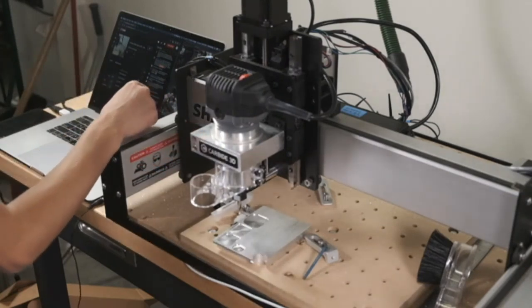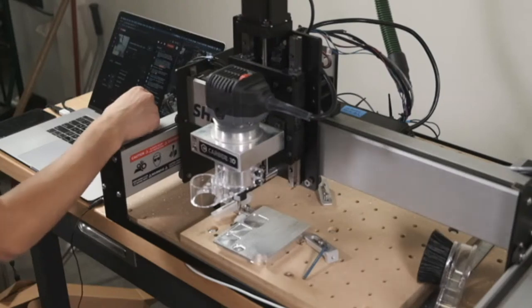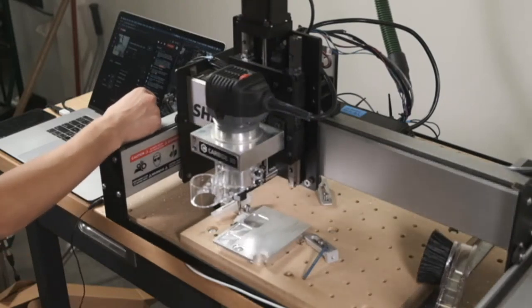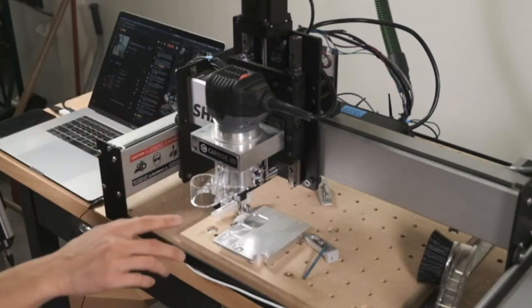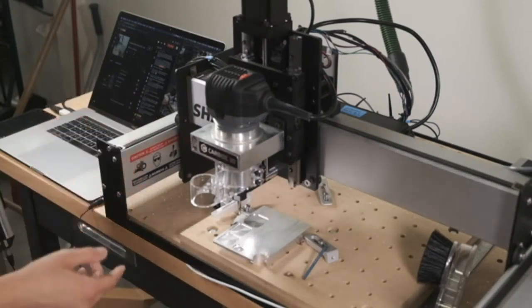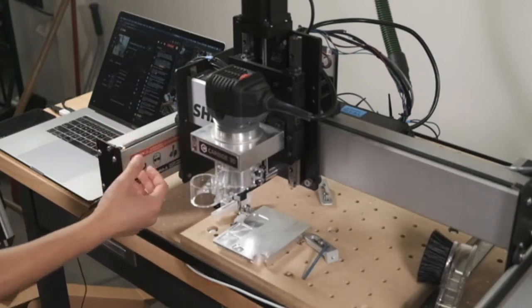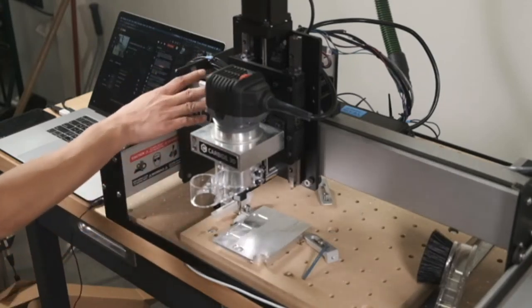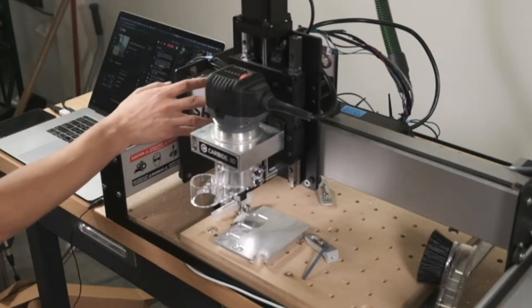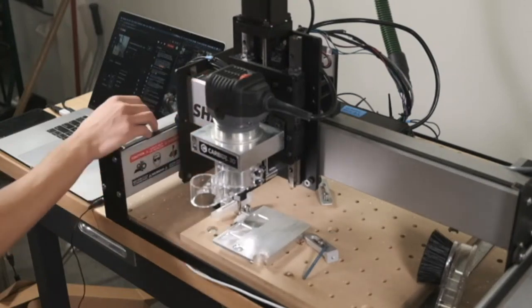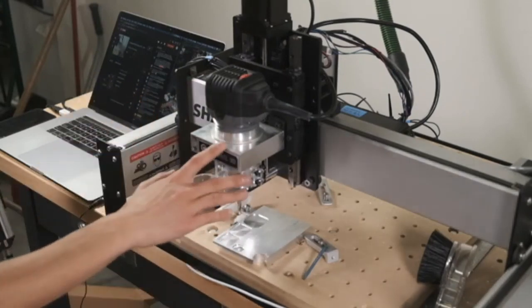So let's see. You totally can use vCarve to create toolpath designs. So this goes back to a bigger discussion. You can basically use any software that has a post-processor that will export G-code that a Grbl-based machine can understand. So Fusion, Vectric vCarve, Aspire, Carbide Create Pro, Carbide Create, MeshCAM, they will all work with the Shapeoko.